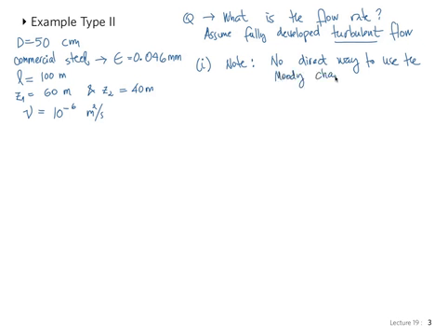Close. Bernoulli's equation, remember, is for ideal flow, so there wouldn't be any head loss, right? Because it's ideal, totally ideal. Energy equation, excellent. Very good. So we use our energy equation between points 1 and 2, and that will allow us to get the head loss, as you very well suggested. Okay? So energy equation between points 1 and 2 in our system.